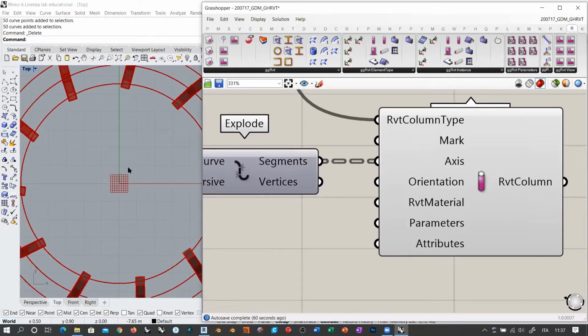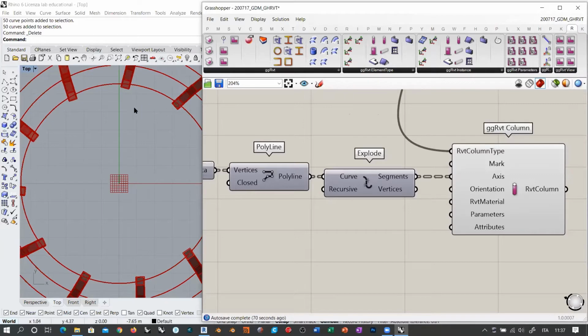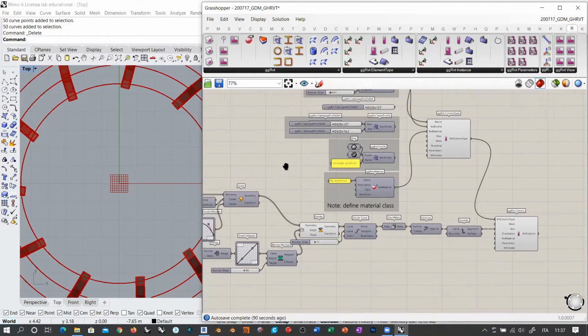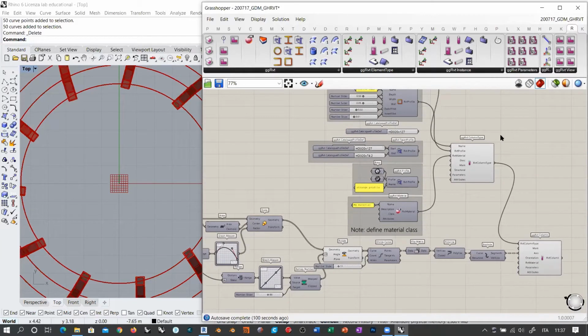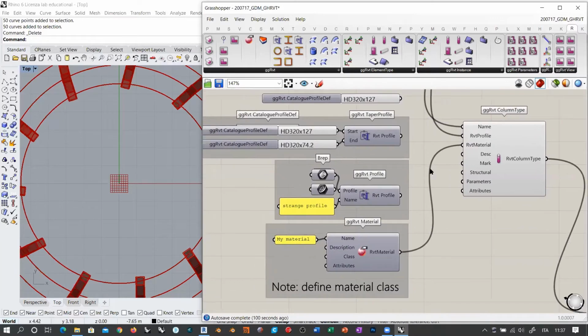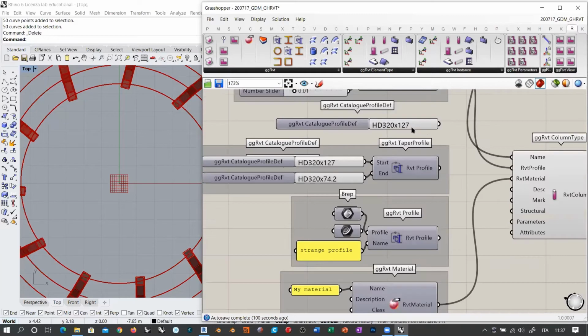Okay, and the orientation depends on the axis. So that's why orientation basically asks for a vector. Now we are working with a square hollow, so it's irrelevant if I change the orientation, okay? Because it's a square. Unless I want to create some weird inclination for this square and make it oriented with an angle with respect to the facade, which is something that I would not recommend for several reasons, also for assembling the structure or manufacturing purposes, but it's not the case eventually. So let's switch back to a standard, well, let's take another profile.